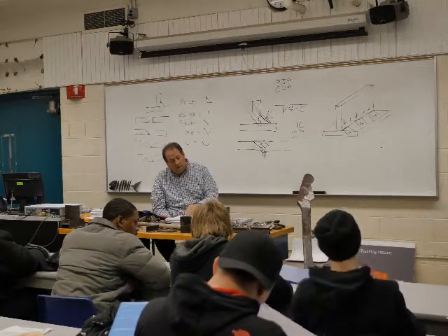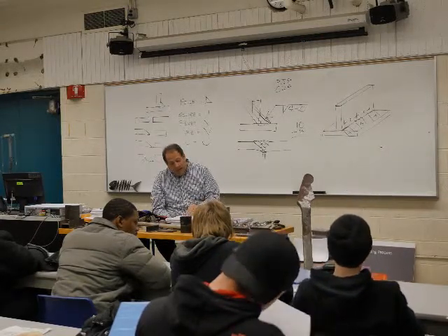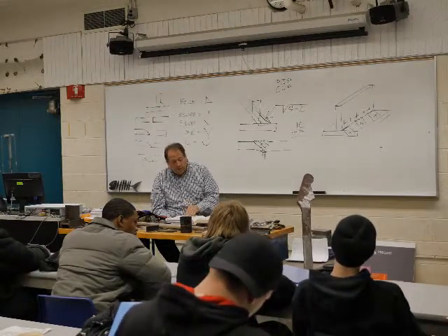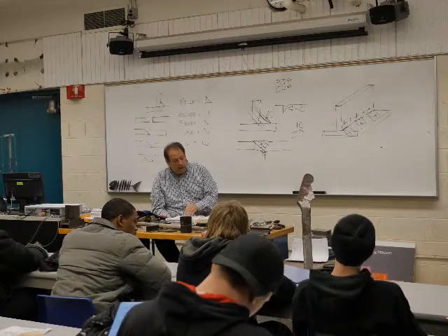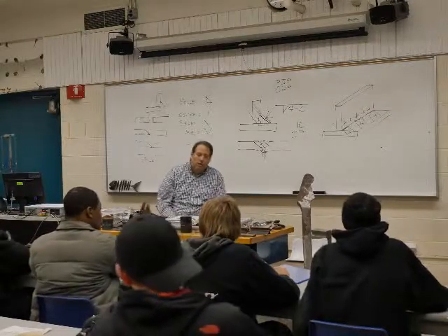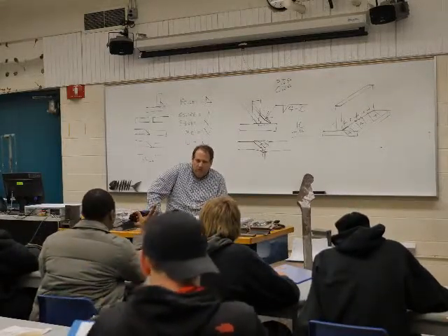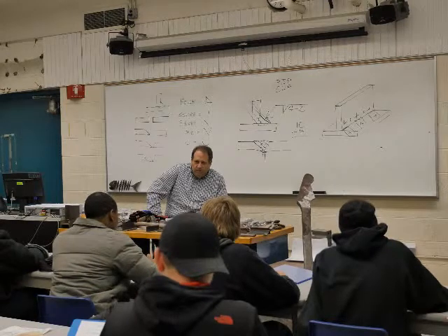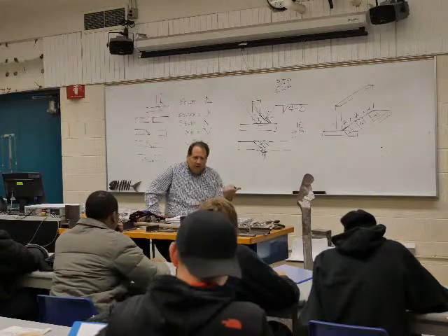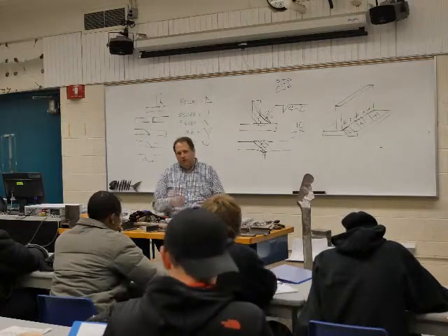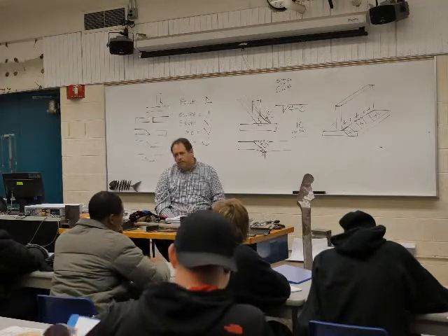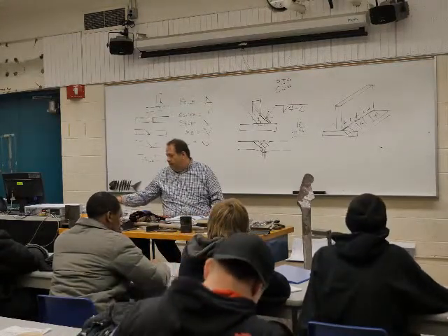The rest of what this is not, like I said, seam welds and stuff, no big deal there. But most of what we just did is what you'll see on a general print. Quick question. The diagram up there, the orientation of the welding symbol doesn't matter? It doesn't matter. I wrote it off to the right, but you'll see some that are off to the left also. It still is arrow side, other side. That stays the same no matter which way it's oriented.